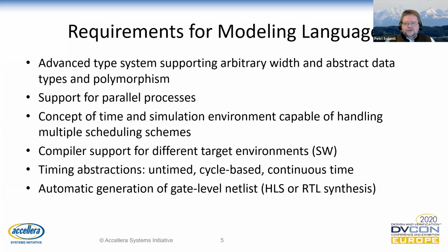Timing abstraction is bound to the model abstraction. Analog behaviors can be modeled with discrete time schedulers to a certain extent, but an accurate analog model requires continuous time scheduling. Untimed domain is needed for fast simulation and in the beginning of the modeling phase. For digital hardware, it is important to have a logic description that can be synthesized to a gate-level netlist for backend processing. So there are lots of requirements for the language that can be used as a single source modeling language for the full design process.